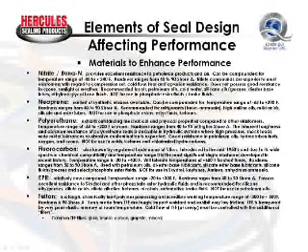Neoprene is typically used for refrigerants, for high alkaline oils, and some other compounds, not for use in phosphate esters, nor is nitrile for use in phosphate esters. Temperature range on neoprene is a little bit higher than the nitrile, and its hardness range is about the same, from 40 to 90 on the Shore A.